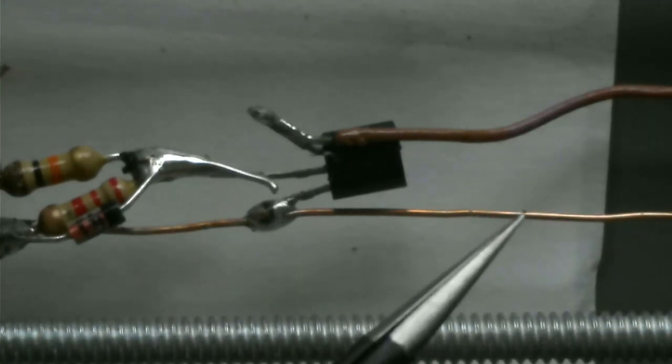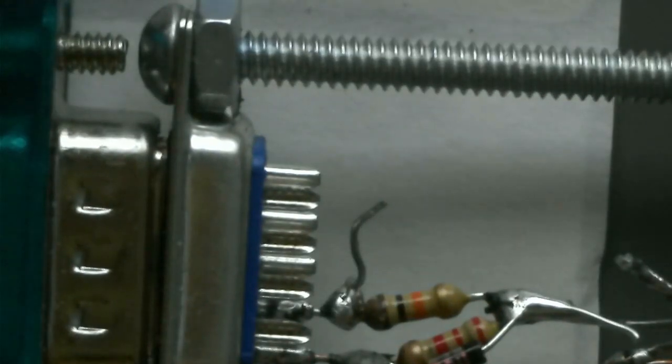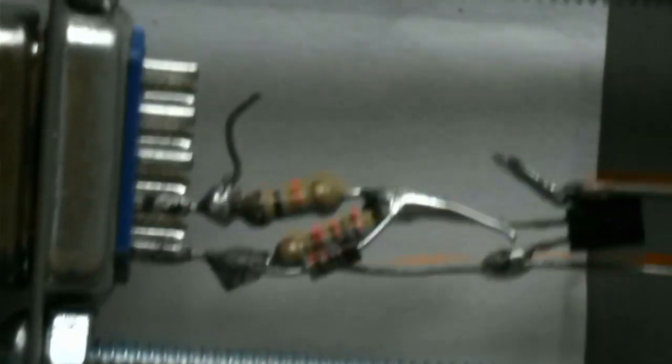And by the way, that's another reason why you just can't plug this in. The ground on the repeater plug is pin 1, and the ground on the computer side is pin 5. So that's another reason why you just can't plug these in and make it work.